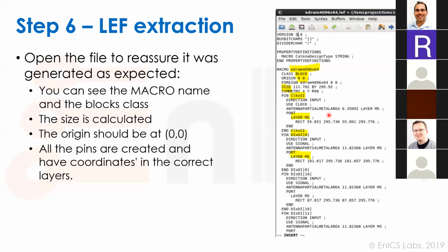It's a ratio that says you count the amount of metal layer during a certain process step divided by the amount of gate, polygate, that it's touching. If it's higher than a certain number, then that is a violation. Okay, so it's something that's very technical. Like to absorb the extra charges and like that?